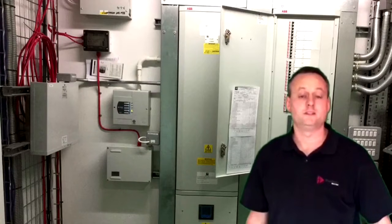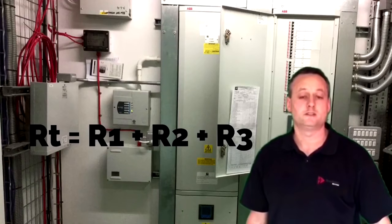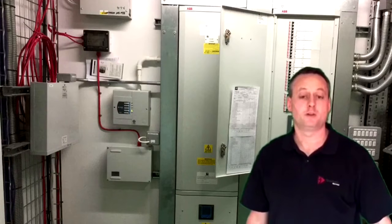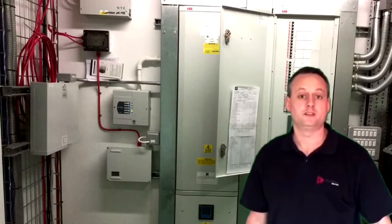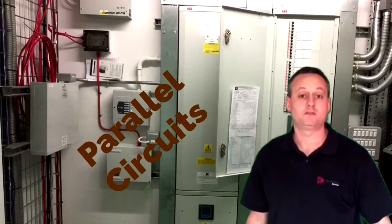The total resistance in a series circuit is the sum of the individual resistors. If you had a resistance of 2 ohms, 5 ohms, and 10 ohms, the simple addition of 2 plus 5 plus 10 gives you 17 ohms for total resistance in a series circuit. Total voltage in a series circuit is the voltage that drops across each individual resistor added together. We then moved on to look at parallel circuits.